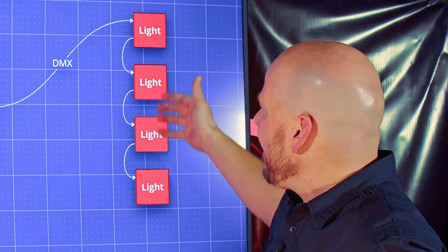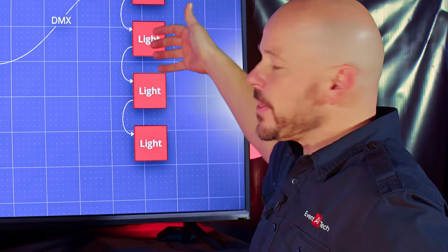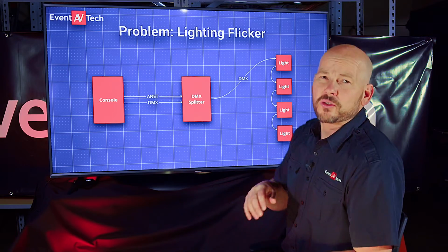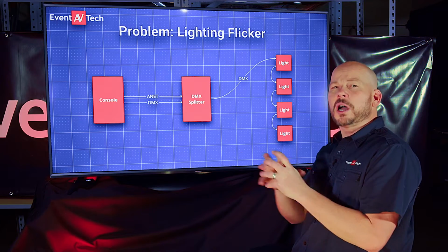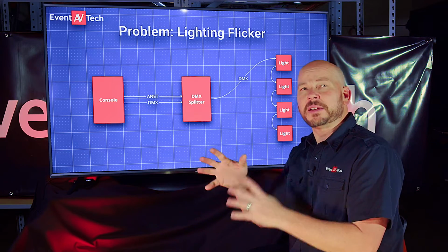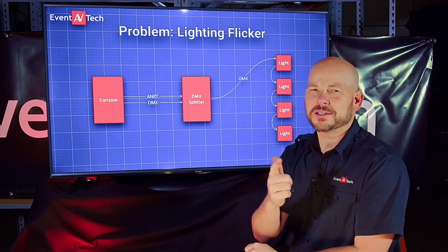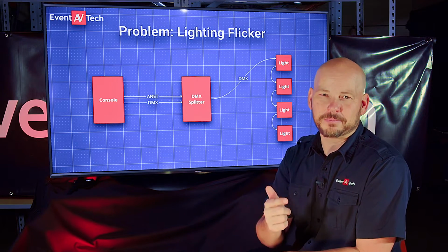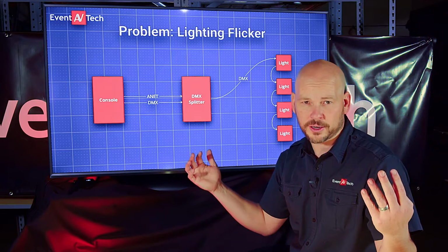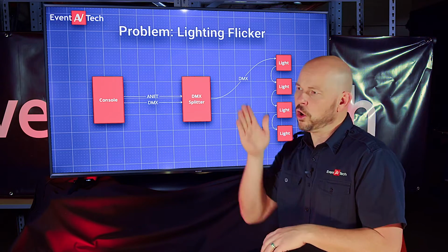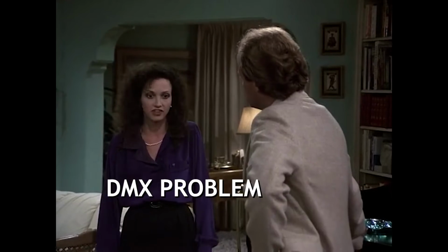When that happens, it can often cause digital noise and cause all your lights to go crazy. Normally, if you've been watching this series, I've said start with the problem. Well, this is a challenge with lighting because normally all the lights flicker on that line of DMX. All of them are flickering, so you can't go, oh, is this the one? Is this the one?